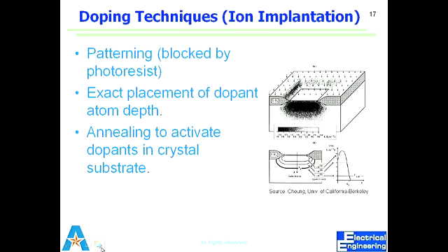The difference between diffusion and ion implantation is only the way they enter the silicon. Once they are incorporated in the silicon, is there a difference in the electrical properties of silicon? No. Then I have read that resistors which are ion implanted have a higher voltage rating than the ones which are diffused. Yeah. So once they get into the substrate, one case does more damage than the other. In diffusion, we are not doing a collision between atoms, right? We are not doing collision between ions and atoms. In the case of implantation, that's exactly what we are doing.